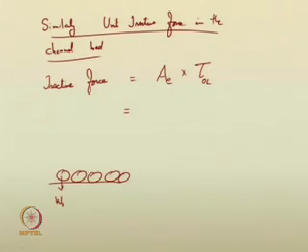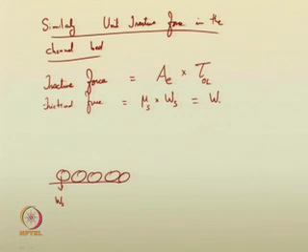There is no component that can cause the movement of the particle. So, you can now write the tractive force as A e into tau 0 L. The frictional force, as we mentioned here, all the component of the weight will be acting for its friction. So, frictional force is equal to again mu s into W s.